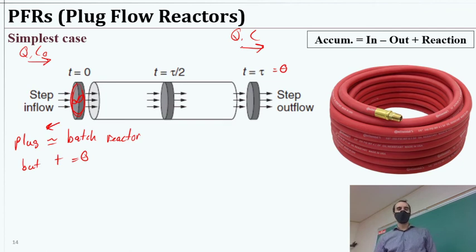So whatever's coming out here is described as if it was a batch reactor, just spending some amount of time in there, and that time is equal to that hydraulic retention time. Okay, does that kind of make some sense? Okay, great. And we'll look at this again with more detail about adding the reaction terms in here next time. Want to have plenty of time to cover that.